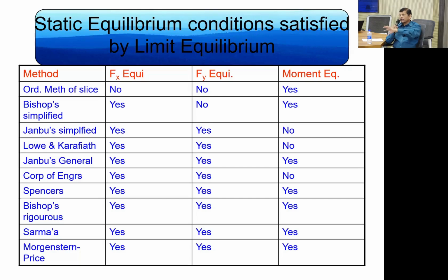I always recommend that whoever does the limit equilibrium model should know what the failure surface should be. Because if you have no idea, then we are totally depending on the software, which is telling us this is my failure surface. We always use software to find the failure surface, but we should see that and make sure it's realistic. Yes. Can you give us some example?